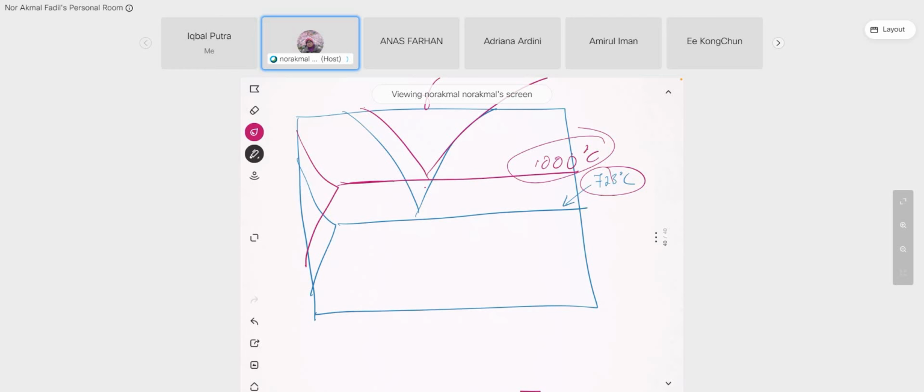If you induce heat on your steel and you reach the austenite temperature, it means the original microstructure of your component will change. If the microstructure changes, it means the properties will change. So whatever the initial design requirement that you set for the component will not be supported by your steel anymore. So make sure if you need to use your steel at higher temperature, you choose the correct alloying element.